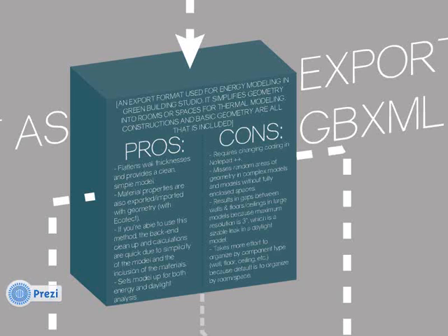The organization is a little bit different. With DWG, you get layers from your CAD naming convention, so when you bring those in, you can group them easily. With the GBXML, it groups things as spaces or as rooms. So it's a little bit harder on the back end to separate walls from roofs from floors to apply certain materials to those, right? With daylight simulation, we're worried mainly about the reflectances of the wall versus the ceiling versus the floor, so it's really useful to be able to separate those. It takes a little bit more work with the GBXML process.